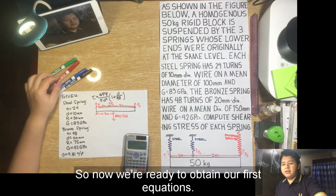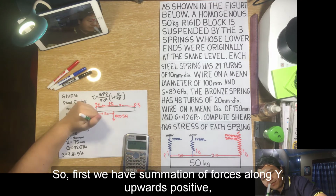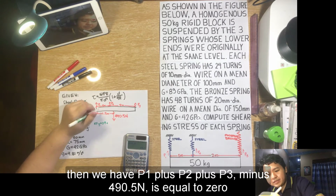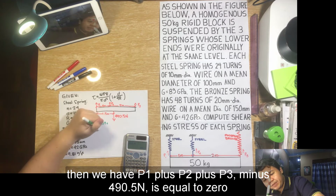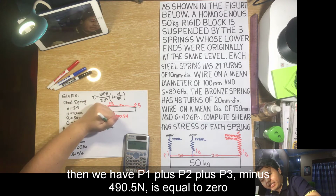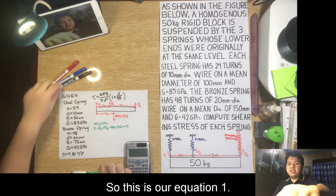So now we're ready to obtain our first equation. First we have the summation of forces along y, upwards positive. Then we have P1 plus P2 plus P3 minus 490.5 newtons is equal to 0. So this is our equation 1.